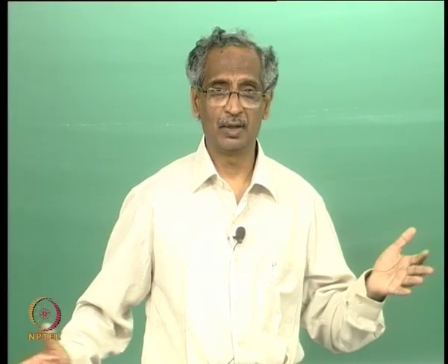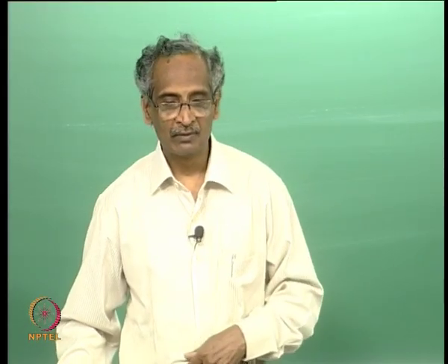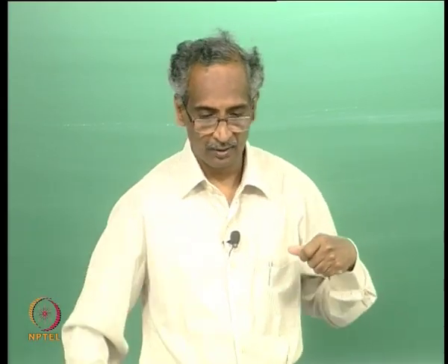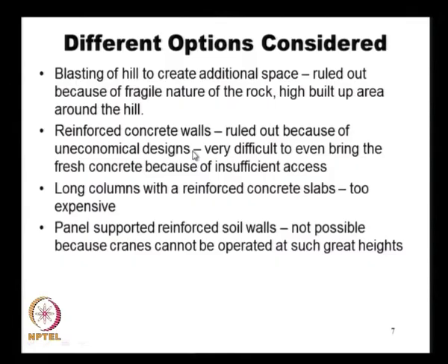So, it will be about 5 to 6 meters wide, and then it is ruled out not only because of the cost factors, but the approach area is so narrow that we cannot bring in the concrete lorries, and so it is very difficult. And then pumping in the concrete from a high height is also a problem, because we need to see how practicable it is to pump the concrete at very high heights.